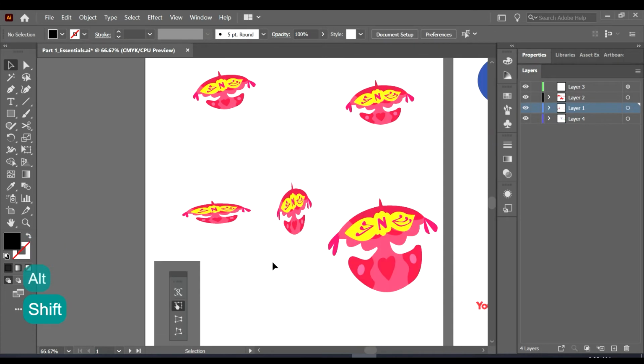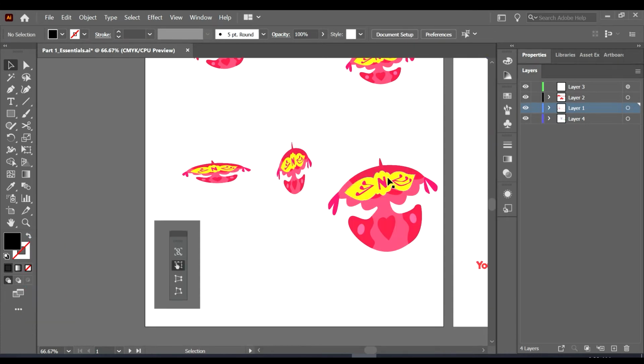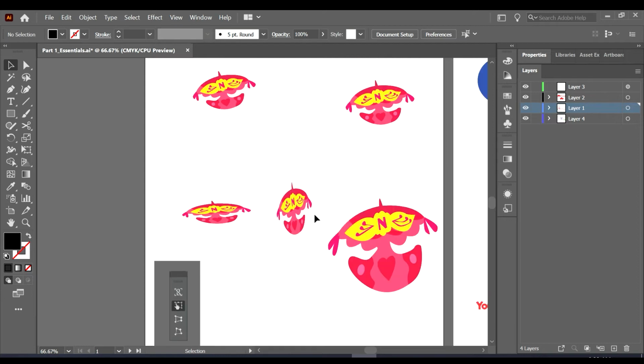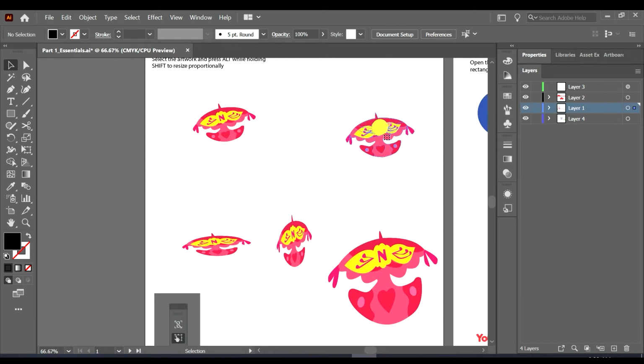Right, so in Illustrator you can also make it skewed like this one. For example, if I select here and press E, you will enable the skew tool over here. You can also use free transform. It has perspective distort and also free distort, so you can play around.